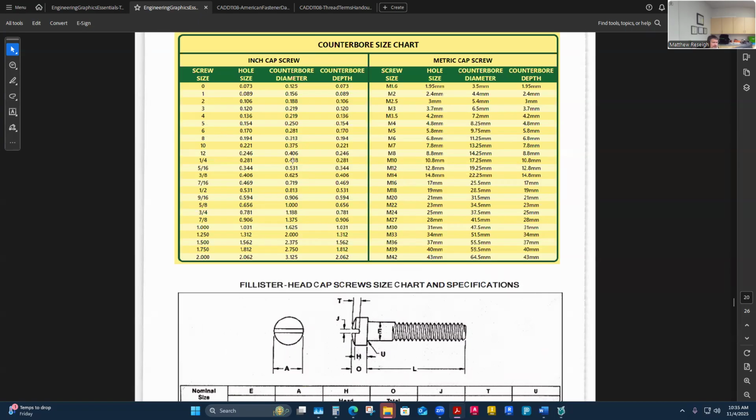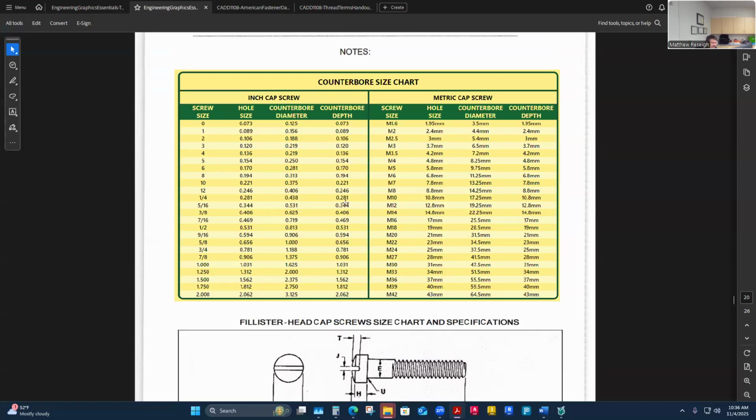Really, from their appendix to this, it's the same here, but this is the one that's given here that's not given on theirs. How deep that head goes is 0.281. There's a few ways you could interpret that from these charts, right? Because the head depth was given as the same as the major diameter. If it's 1/4 inch, then the head should be 0.25. So what I like about this is it shows that it's just slightly oversized. It's not that this is a great example, but this is a little bit more than 1/4 inch.